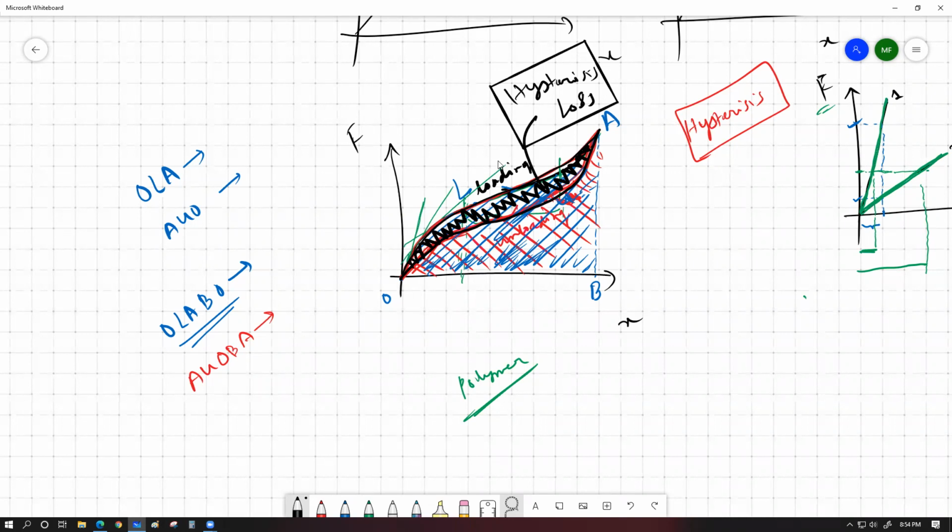And if we keep on loading and unloading a polymer substance, for example, a rubber band, if you keep extending it and letting it back to the original dimension multiple times repeatedly, then the specimen is going to store this amount of energy within itself for every cycle. This is going to slowly heat up the specimen. This will definitely heat up the specimen. So if we have some polymerized substances which are going to undergo continuous processes of squash and expand, it is very important that those polymerized substances should be cooled properly.